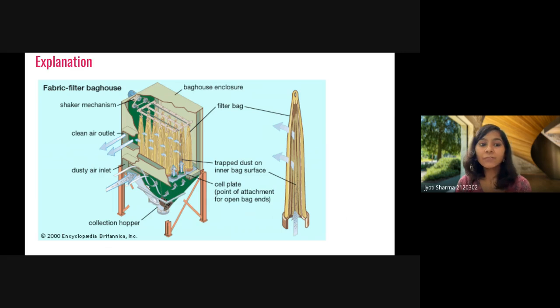Then this is your fabric filter. We have a fabric-made filter, because fabric is woven and has some pores. So whenever the gas crosses, the particulate matter will stick to your fabric filter, and this is how we can remove particulate matter using a fabric filter. Now we will talk about such kinds of technologies and instruments one by one. So I don't think that there is any problem. We will start with the gravity collector. Let me remove this.